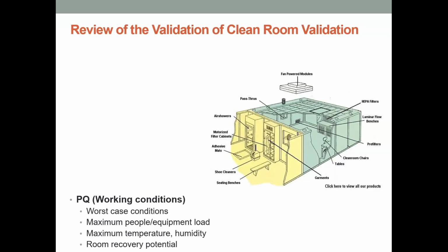The PQ, what we've done for this lesson, we've looked at our working conditions. So what are worst case conditions, looking at our upper and lower limits for our specifications for the room, and how can we test those and challenge those. So the maximum number of people, the maximum amount of equipment or load in the room, how did it work with that? What were the maximum temperatures and the maximum humidity you could go to while still remaining within specification? And again, looking at our room recovery potential. So all very important factors in the validation of a clean room.